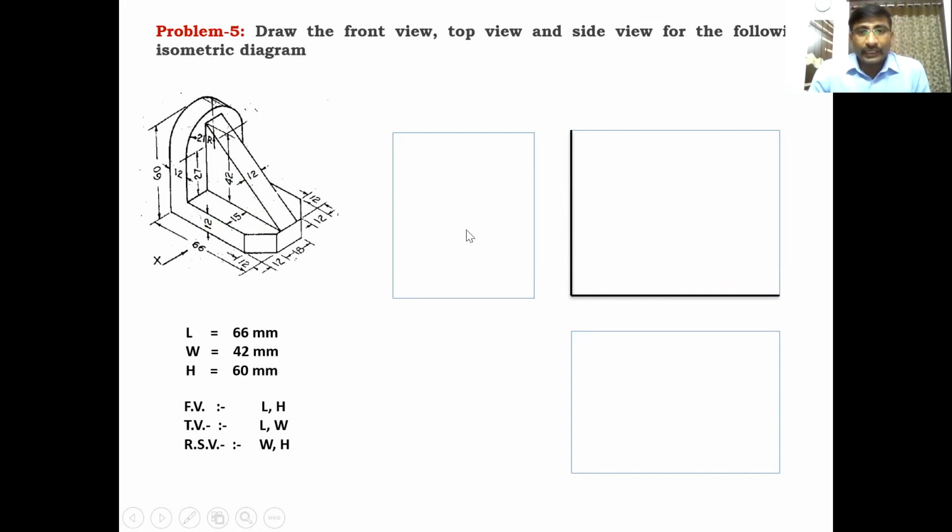Okay, and then this height is given as 12 mm. So draw a line of 12 mm height. Here the width, this width also, is given as 12 mm. Then draw the vertical line from that point and draw the horizontal from this point. It looks like an L-shaped surface. Okay, L-shaped surface. And another edge is there here. This edge is at a depth of 12 mm from one end. From this end, at a distance of 12 mm, we draw a vertical line.